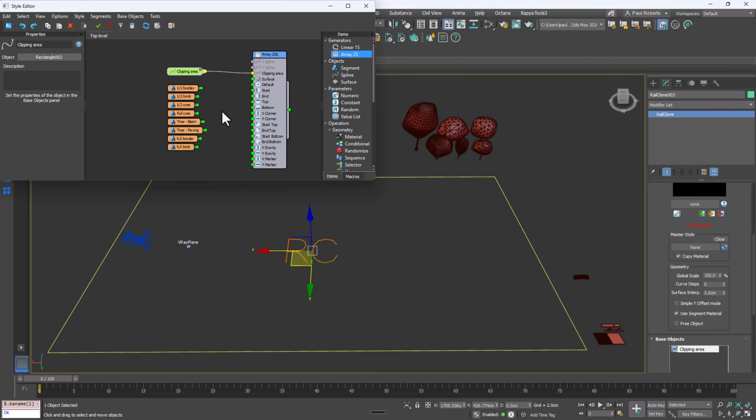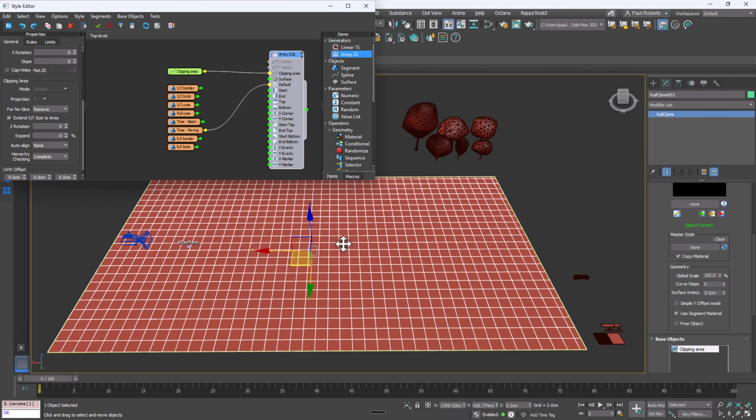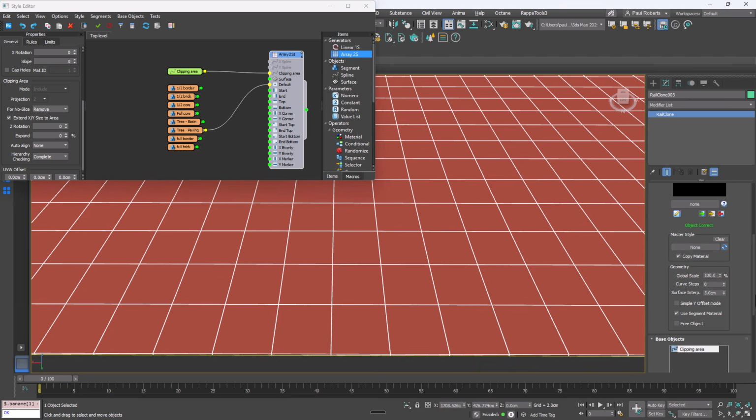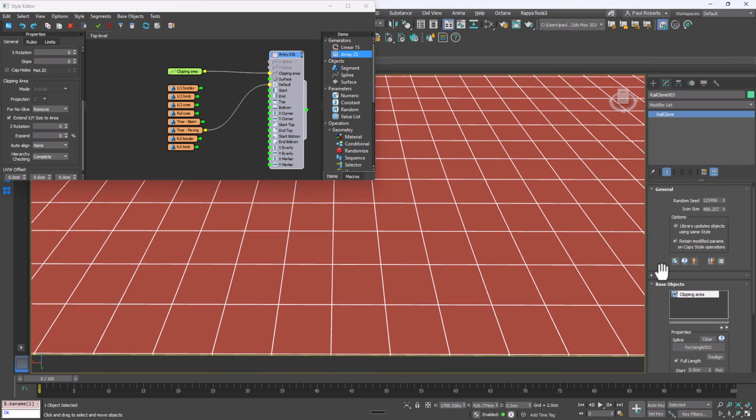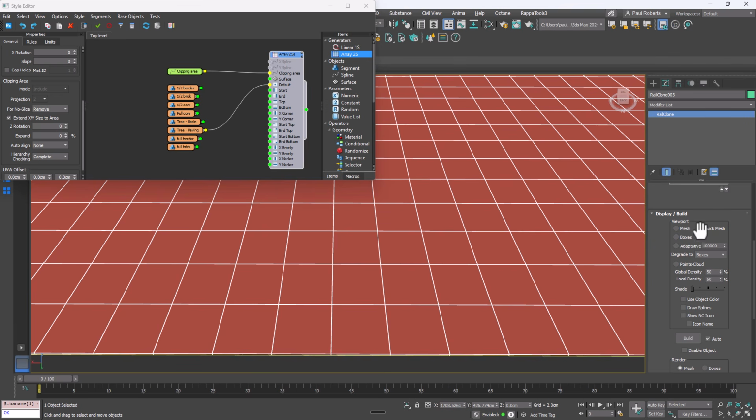We'll start by creating the row containing the large slabs and the tree basins. Wire the large paving slab segment into the generator's default input. To make it easier to see what's going on, go to the RailClone Objects Display rollout and make sure Quick Mesh is enabled. At the moment, the area contains only the regular large slabs.